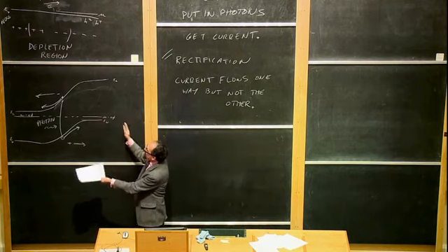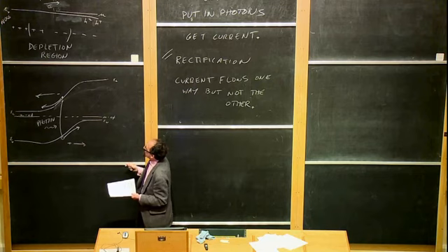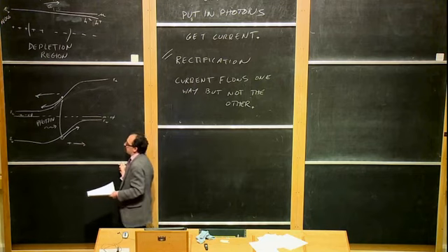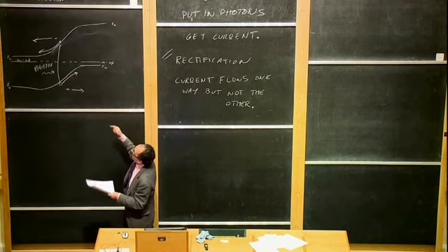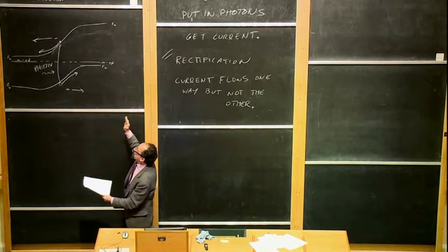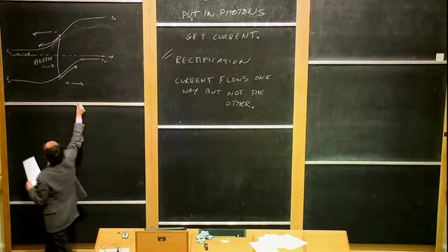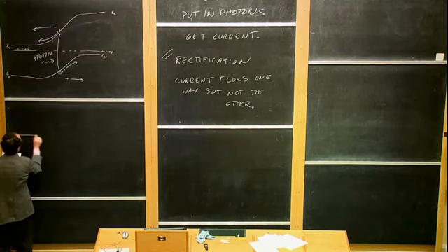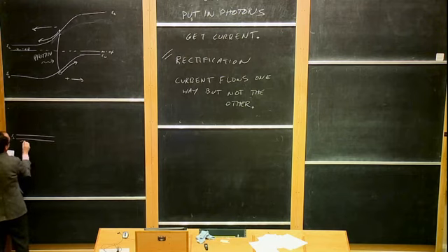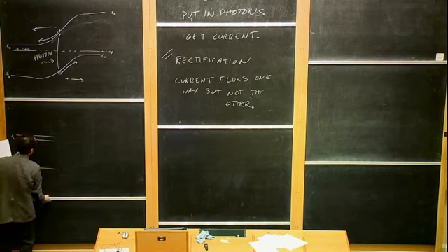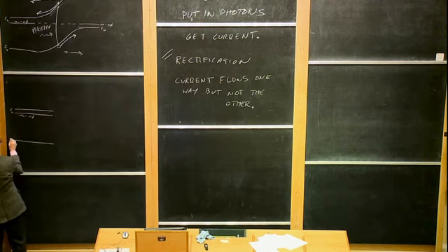So okay, let's take this device and let me draw the same picture again, except now I'm going to put a voltage across this picture to try to get current to flow. So let's do that. Draw exactly the same picture. EC, here's the electrochemical potential, mu minus E phi on the left. And then down here is the valence band energy, E valence.